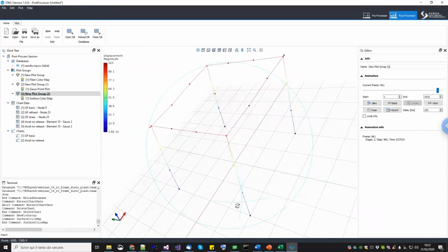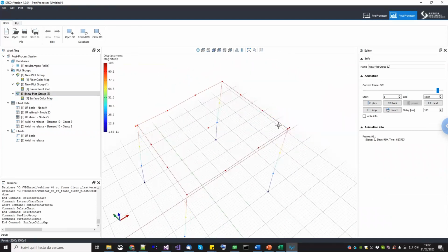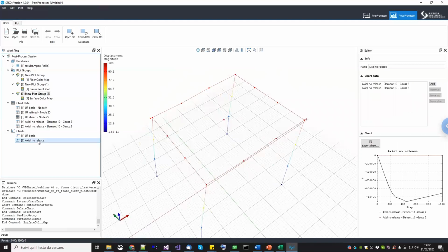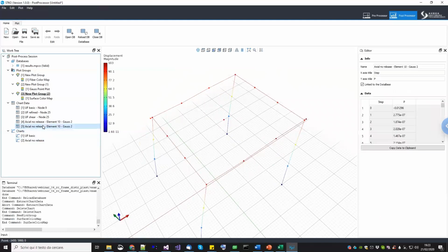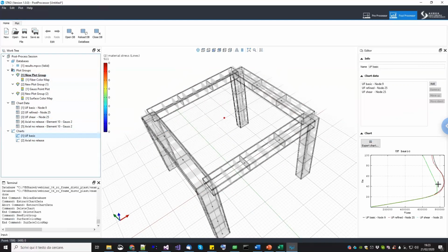So this is one way to get rid of the problem. Otherwise, you can just draw your slab, so you will consider the actual real axial stress, the stiffness of the slab. Okay, so now I'm going to unlink this one, and also okay. Yes, something that we need to do now is actually to extract the load displacement curve so that we can compare it with the previous one. So this was the response with shear, but with the effect of the rigid diaphragm. Now let's see what changed.